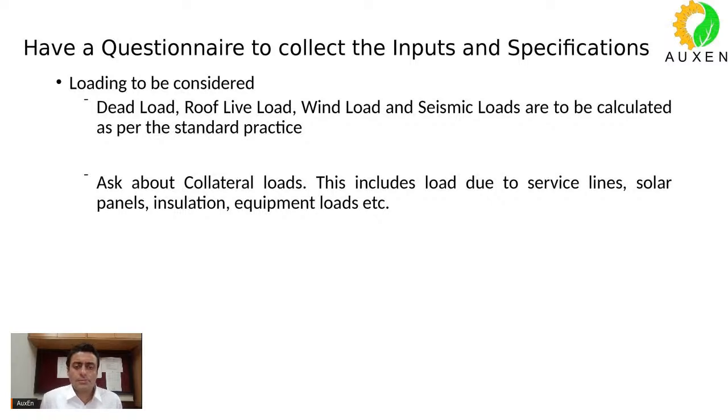Okay, so those may be due to service lines or air conditioning ducting, or maybe due to any equipment load, any solar panels, or anything other than the loads that you have considered. Any other load, if it is possible that your structure may have to take, you must always ask your client about it. Okay, very important.